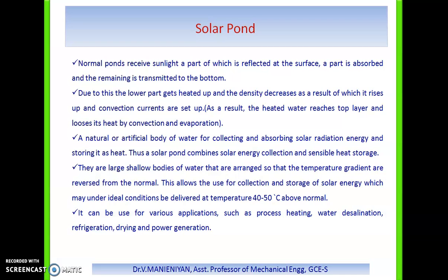A bed of insulating material under the pond minimizes the loss of heat to the ground. A curved cover made of transparent plastic or fiber glass over the pond reduces the radiation losses as well as the convection losses. In suitable climates, the pond water can become hot enough for use in space heating, agriculture or other purposes. The water soon attains a fairly uniform temperature.